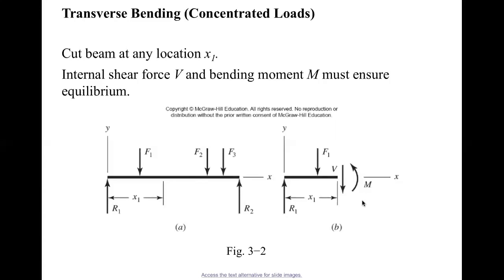So in solid mechanics, we ask you to sketch, I hope you still remember, the moment diagram and shear diagram. So usually the bending moment M changes with the location. So it changes with X. At a different location, the bending moment is different usually.